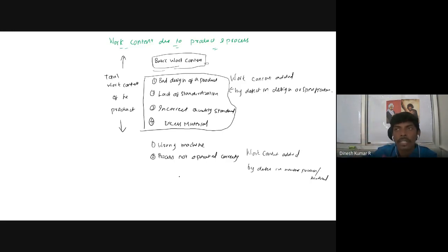So the process not operated correctly. This process is clamping. The only thing is this has to be arrested by something. But again, instead of this side, if you put this side, this will be more legible than this. So if you are putting this side instead of this side, the process is operated but not correctly. In that condition, this will not have proper fixture and this will wobble when you consider your machining, that is your lathe machining process, turning process.